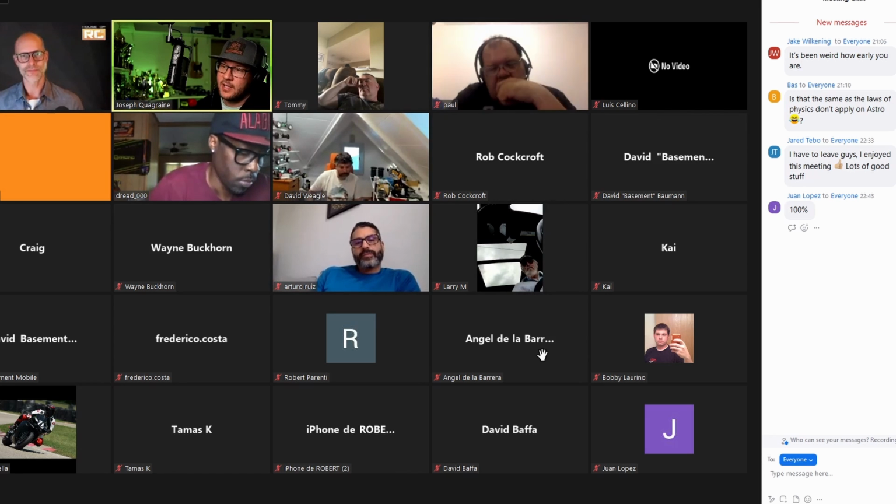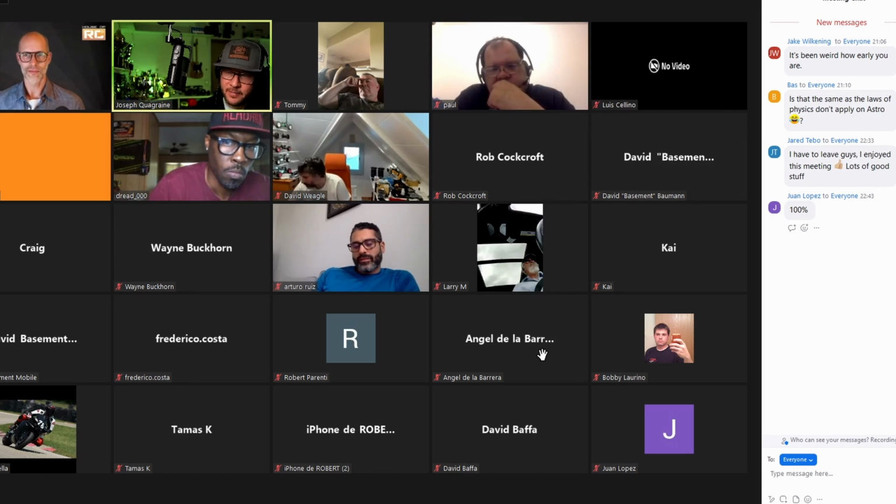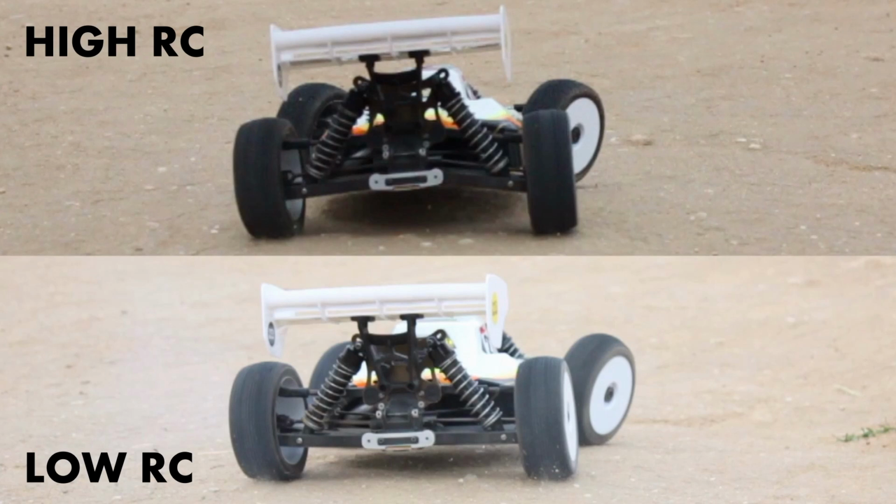Yeah, I would like the Astro boys to try really thick shock oil and big holes in the piston. So maybe fewer holes, but really big, and then really thick oil. Like, it's actually on the table, it feels super thick, and then quite hard springs, but then thin roll bars. So, bigger holes than... even bigger? Bigger holes than 1.6?